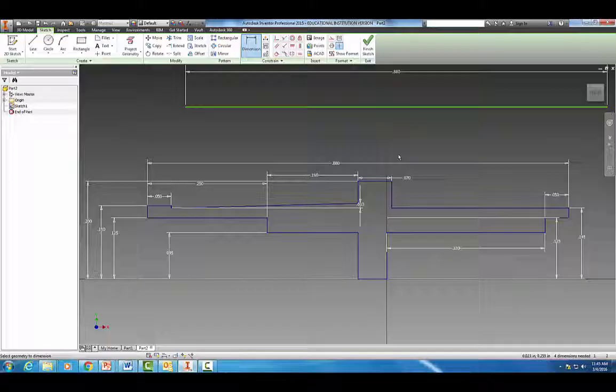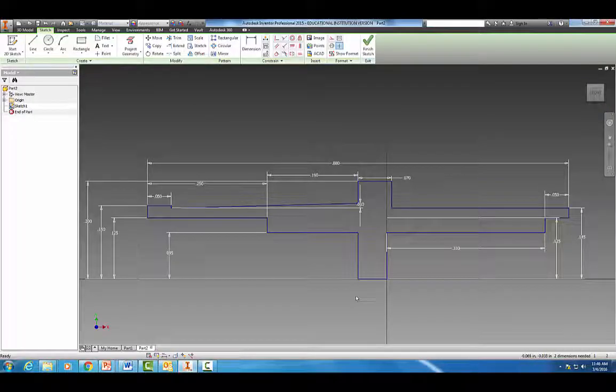Okay, so now if your drawing's a little out of spec, one thing you might want to try is dimensioning: click on that point and click there, and that should be 0.9 divided by 2, which should hopefully move this so that it looks a little bit more like our drawing. Okay, so now I'm going to go ahead and delete these other lines that I just used for scale.